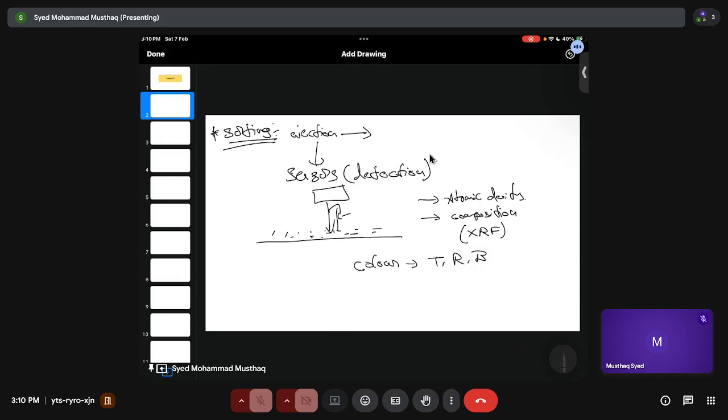And sorting also needs a strict initial processing, because, for example, if I want to separate two phases and I take a very big particle, then these phases may be interlocked, right? That's what we studied in the previous session, the locking, interlocking. If you don't break this, these phases will not get separated. So there are some strict things that need to be considered whenever you are trying to do sorting. And again, the operating costs are large if you are involving a pre-treatment process, right?